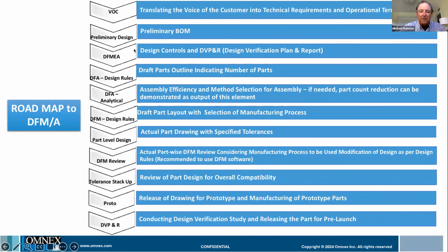Voice of the customer, give me the original design. You were saying earlier, do a design FMEA, apply some design rules with that checklist, do some design for assembly even further. That's the evaluation. Now the evaluation piece, evaluate the individual components for design for manufacturing. Apply checklists there. Pick a DFM check or rule that you want to use. Apply it. Have a DFM review. Tolerancing at the end. Now, at this point, you're ready to go. Get to prototyping, and you can do your DVP&R afterwards.